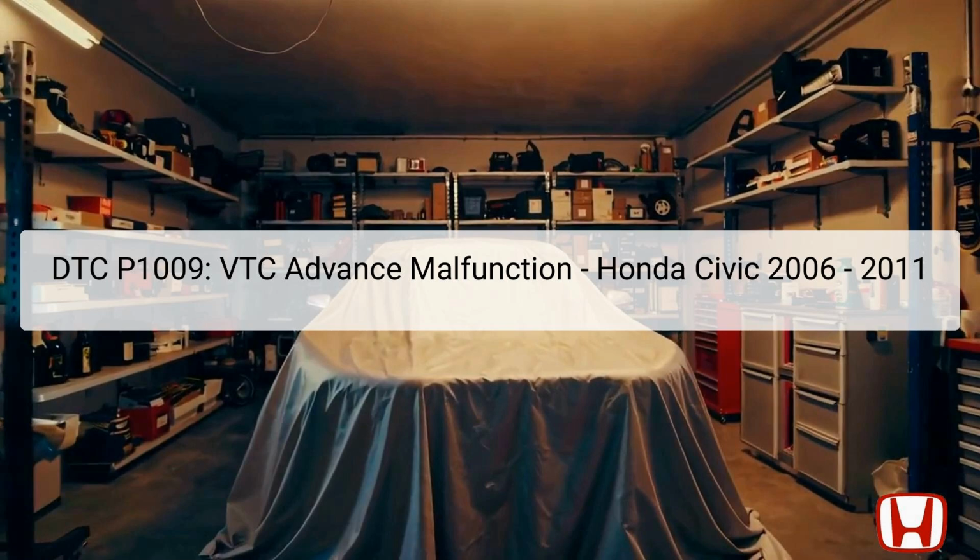The malfunction could stem from several components involved in the VTC system, including the VTC actuator, the oil control solenoid valve, or potential blockages in the oil passages. When the engine is running, the VTC actuator is responsible for adjusting the camshaft's position based on the oil pressure, which is controlled by the solenoid valve. Given the importance of these components, it is essential to troubleshoot this error methodically to restore full engine function.